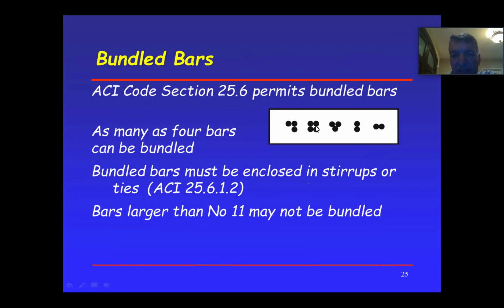So let's look at that. You can bundle bars like side to side, up and down. You can do this, you can do this. The most efficient one from my experience is this guy. When you stack 2 on top of each other, you don't violate the clear spacing between that. This will affect the clear spacing, this will affect, this will affect. Again, in my practice, very seldom I had to do this. And when I had to do it, I went with this arrangement. So you don't do it a lot, but sometimes you have to.